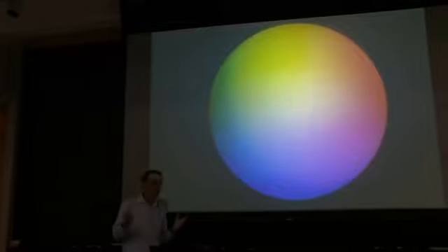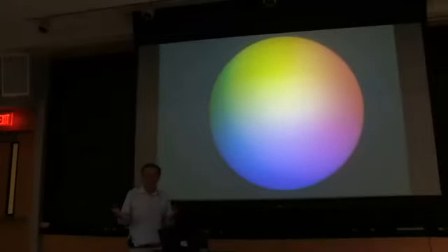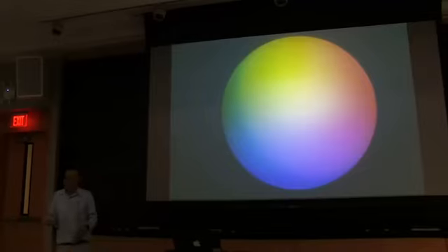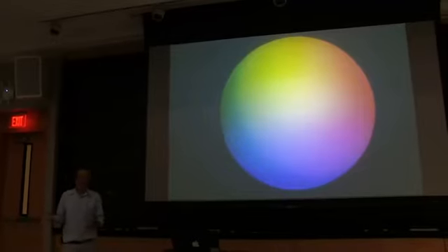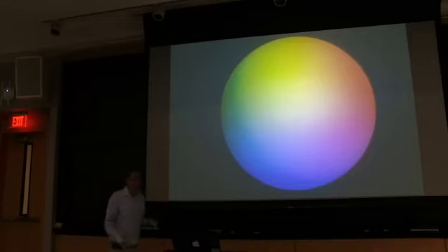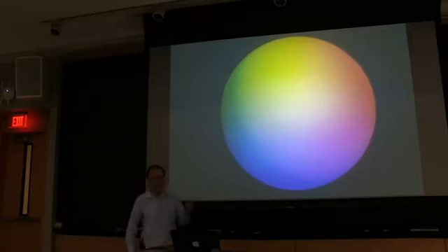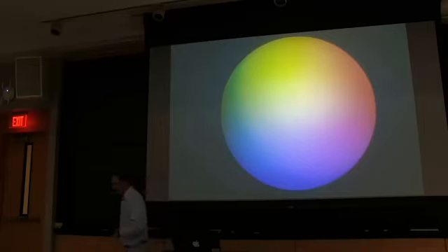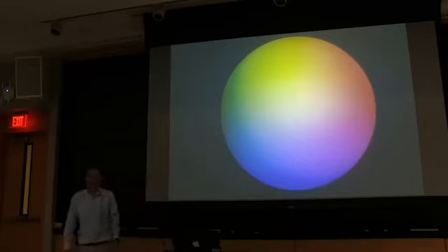Why worry about it? Well, images are noisy. First of all, a lot of the images you're looking at are 8-bit images. That's 1 part in 256. That's really crude quantization, and you can't even trust the bottom 1 or 2 bits of those. If you're lucky and you get raw images out of a fancy DSLR, you might have 10 bits or 12.